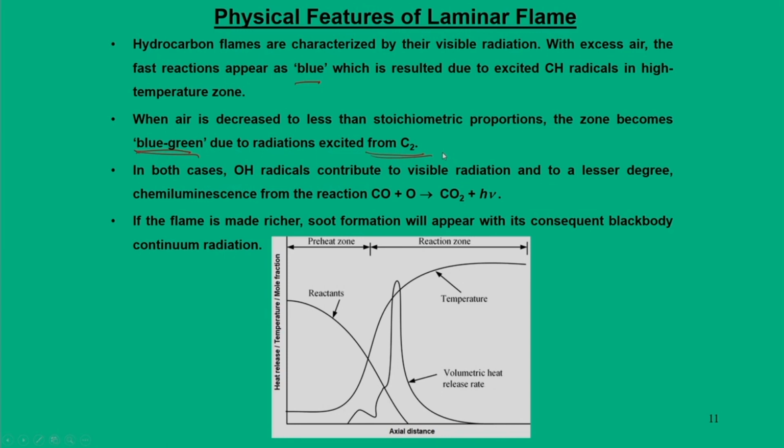Now, further when you enter into a richer zone, that means when the flame gets more and more rich, it is obvious that we will have soot formation. And this soot formation we have already analyzed, that with rich mixtures soot formation is a very common effect. When we analyzed soot formation, we analyzed it from the viewpoint of chemical reactions. Here we are going to look at the viewpoint of the flame.